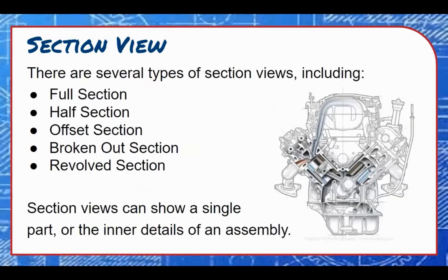There are several different types of section views that we'll be looking at in this lesson, including full sections, half sections, offset sections, broken out sections, and revolved sections. We'll also see how section views can be used for assemblies as well as individual parts.